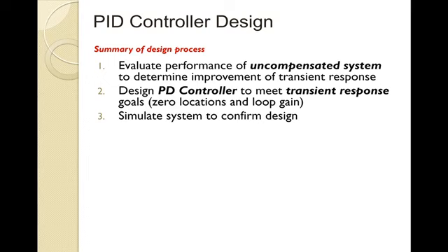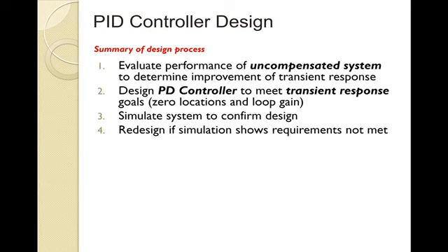The actual numbers were what we had predicted from theory, but a lot of times we are making second-order approximations of third or fourth-order systems, and if they're close enough, the simulated values in the parentheses were very close to the predicted ones. So we always want to do some simulations to confirm that our approximations were indeed good ones.